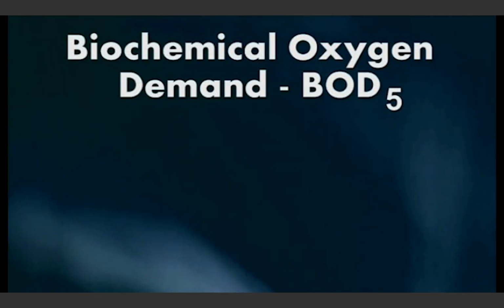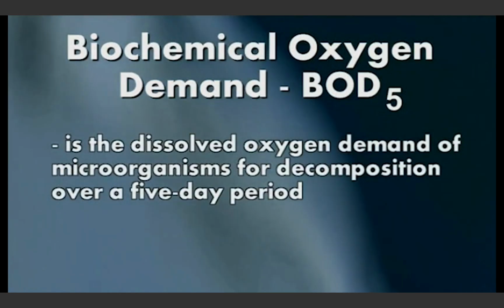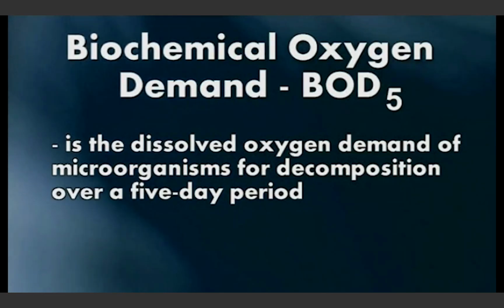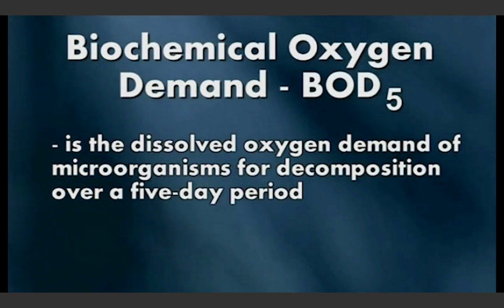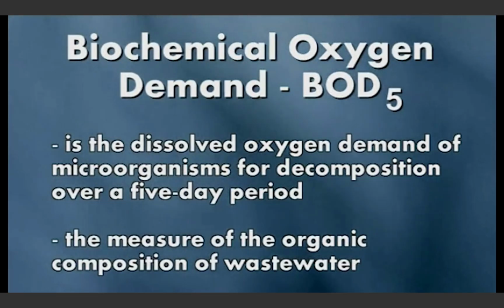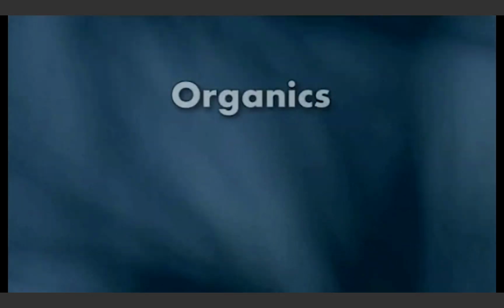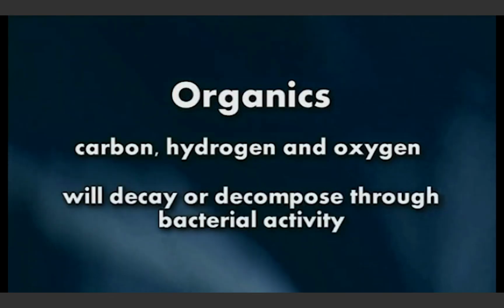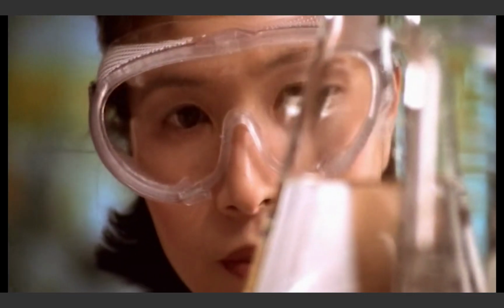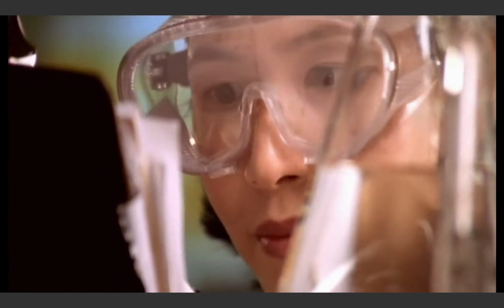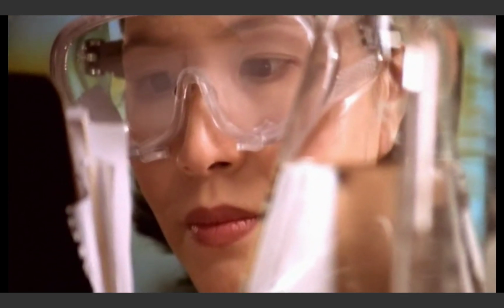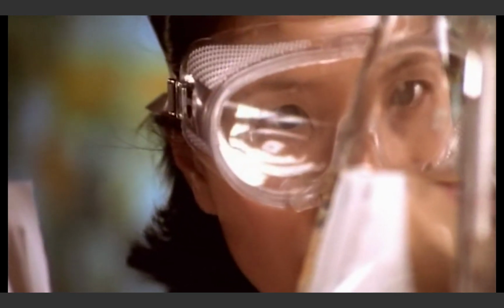Biochemical oxygen demand, or BOD5, is the dissolved oxygen demand required of microorganisms for decomposition over a 5-day period. Or more practically, it is the measure of the organic composition of wastewater. Organics contain carbon, hydrogen, and oxygen and will decay or decompose through bacterial activity. These tests are used to determine the approximate quantity of oxygen that will be required to biologically stabilize the organic matter present. BOD5 is also used for compliance.